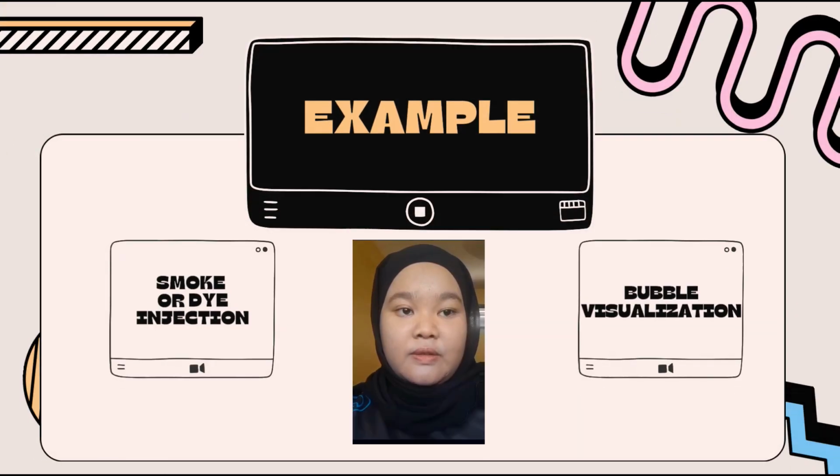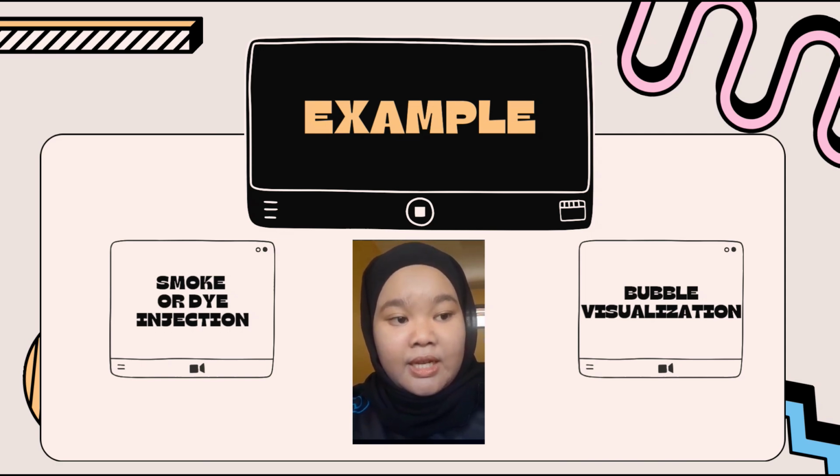Examples of flow visualization that I include in this slide. The first one is smoke or dye injection. Introducing smoke or colored dye into the flow to visually trace the fluid movement and identify flow patterns. The second one is bubble visualization. Creating bubbles in the fluid to visualize flow structures and patterns.